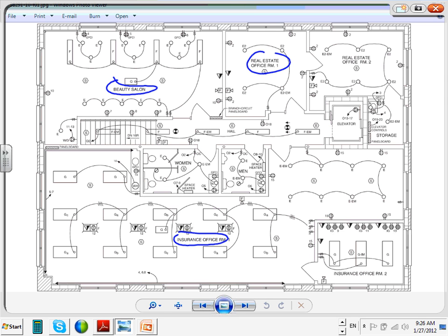So it's a layout of a multi-occupancy building. They call it a multi-occupancy building. It shows the power and the receptacles. A few things I'm going to highlight in this. Remember, guys, the multi-outlet assembly that we were talking about? They're doing a multi-outlet assembly right in here and right in here. If you look at that, they have a multi-outlet assembly that's fed from 3-phase, with multiple receptacles in this insurance office. That's what I want to highlight. Now, is this the only way of doing it? No.